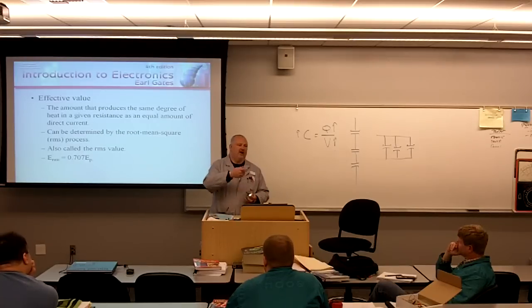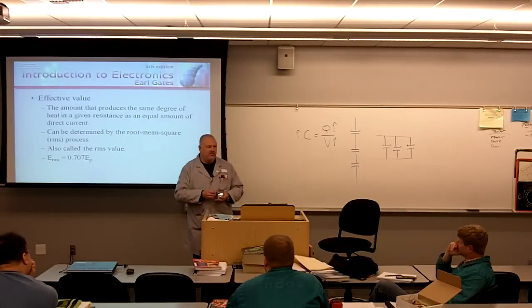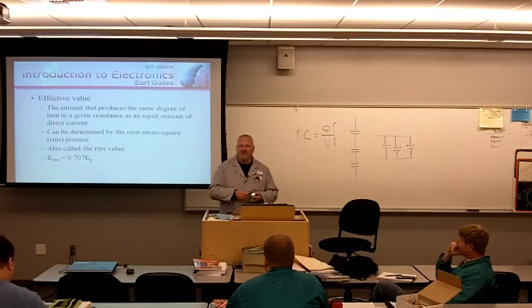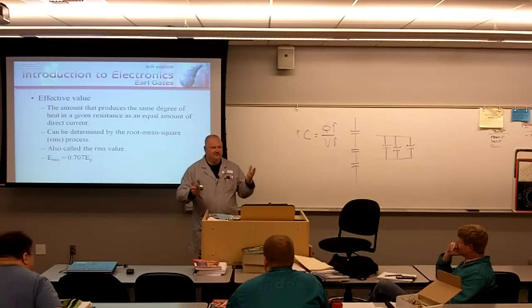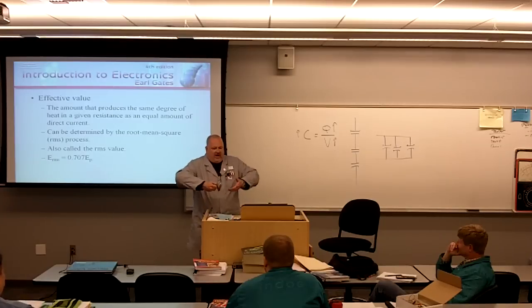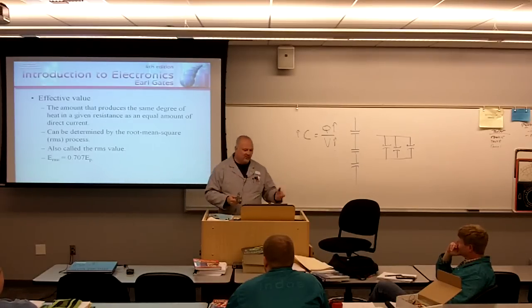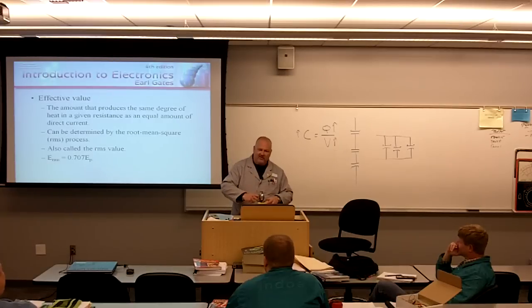So the key is understanding what you're being given in a technical document and why they're referencing that. That's one of the classic things in audio that used to crack me up. 1,000 watts peak. Well, the thing is basically a resistive load, so RMS is going to have the real effect on power, but some marketing dude figured, wow, peak sounds more powerful.